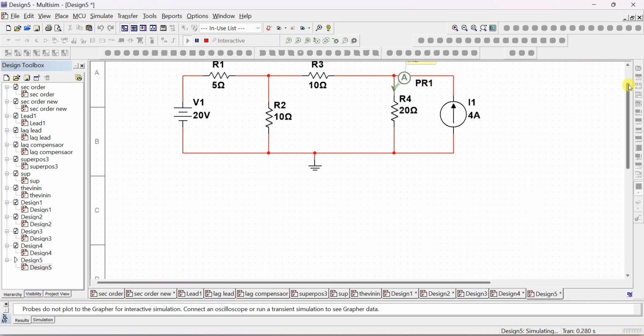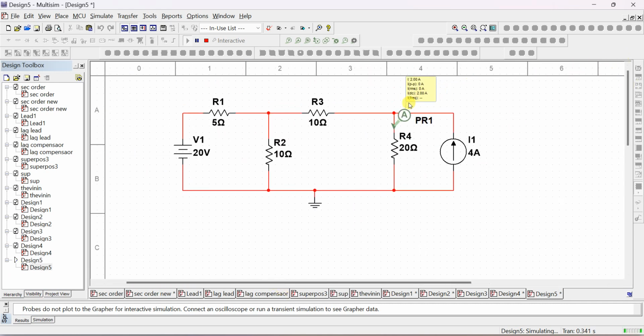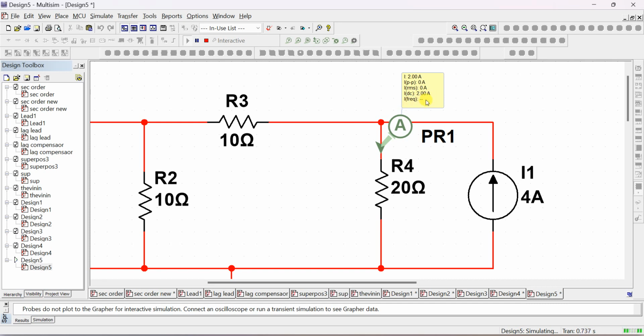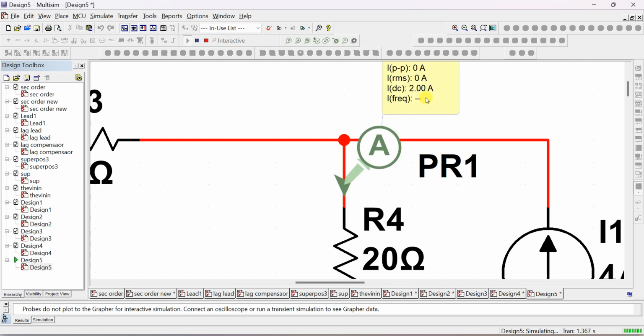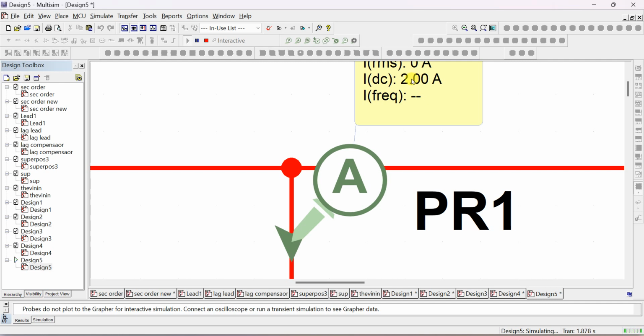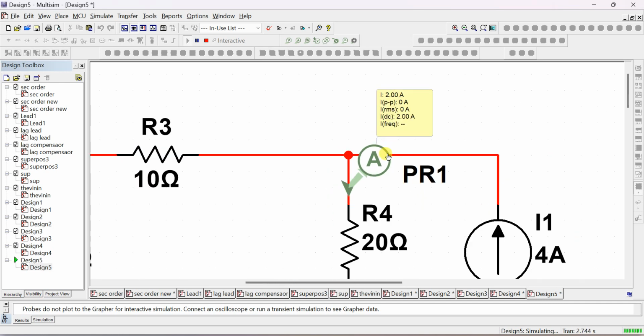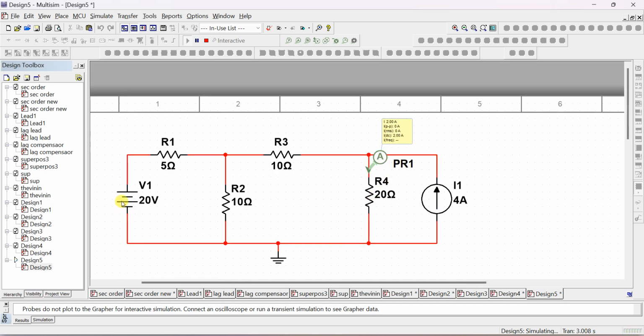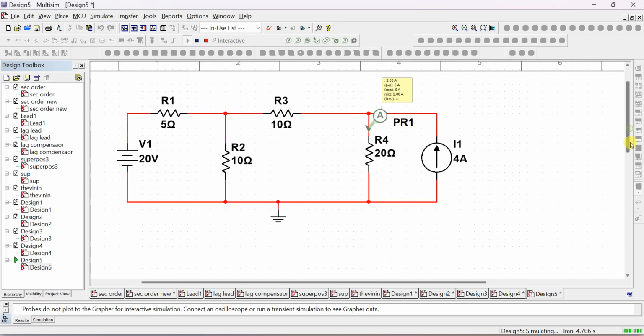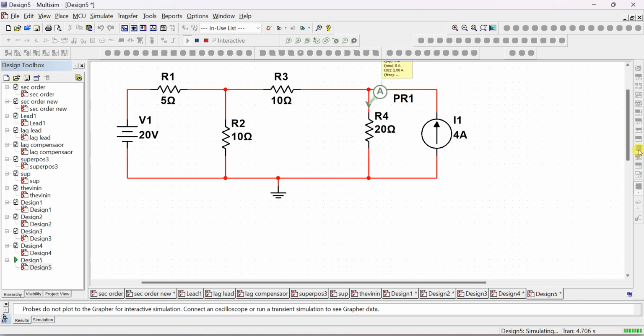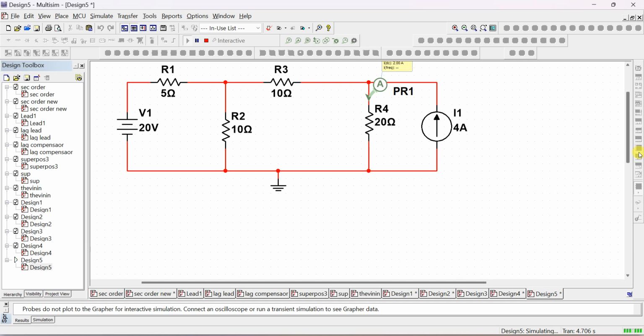This is normal. We are not applying any Thevenin's theorem. So this current you should get in the reduced Thevenin circuit. So the expected current in the Thevenin equivalent circuit is also 2 amps, which you should get with the reduced simplified network, which consists of one voltage source and one resistance. Then your Thevenin's theorem is verified. Okay. So now to find what is the value of that voltage source and resistance.